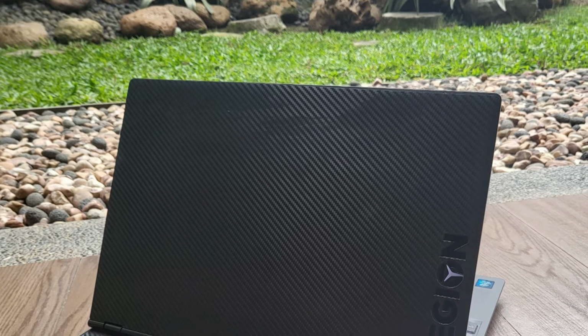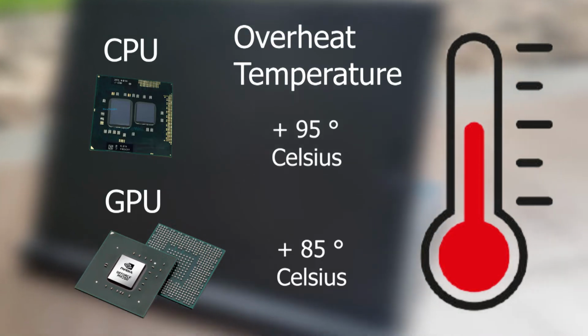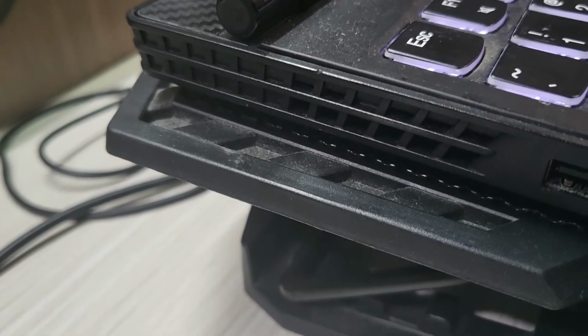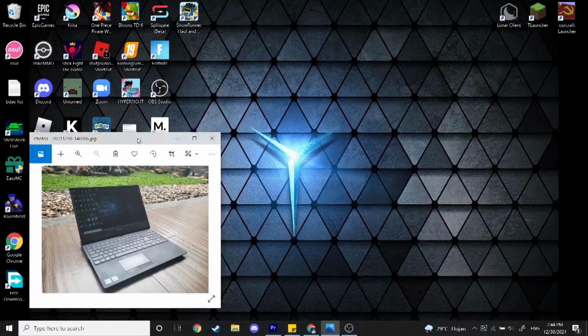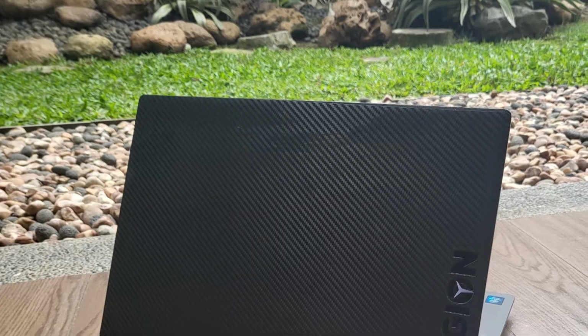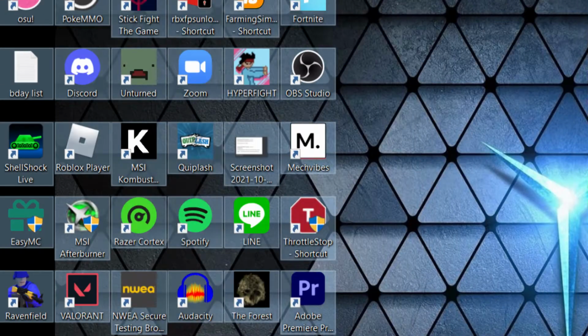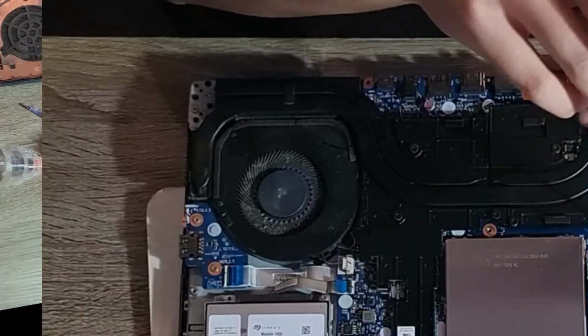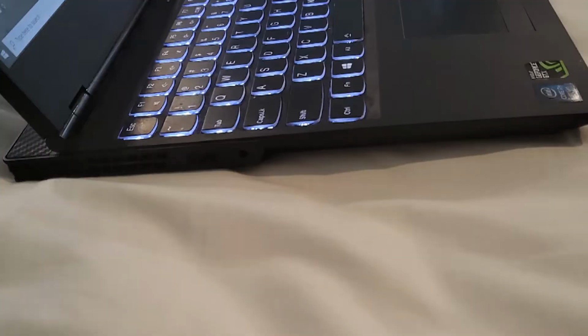Now, an overheating laptop is a phenomenon where a laptop's CPU or GPU temperature is beyond the recommended temperature from the manufacturer. Signs of overheating could be identified from loud fan noises, hot laptop surfaces, or slow or jittering performance issues. There are several causes that could lead to a laptop overheating. It includes running heavy programs, blocked fans, broken components, dried thermal paste, or lack of ventilation.